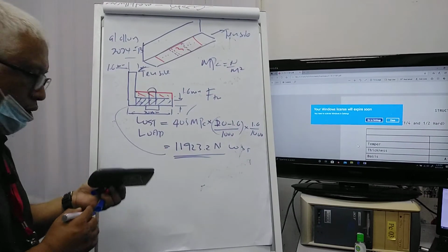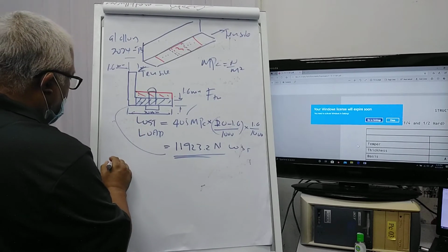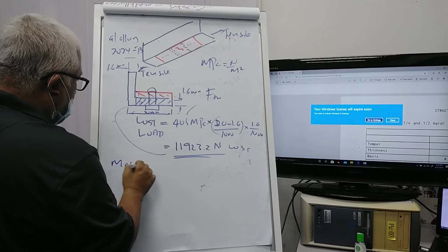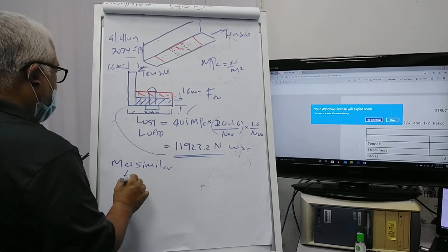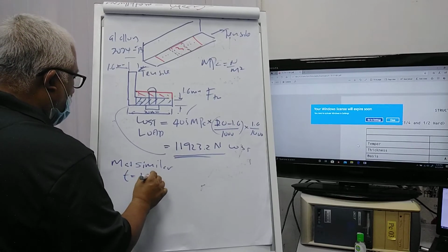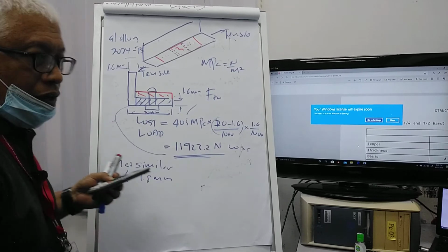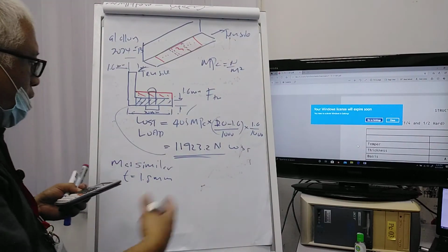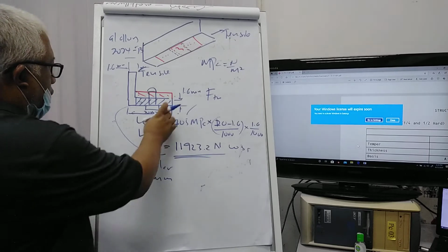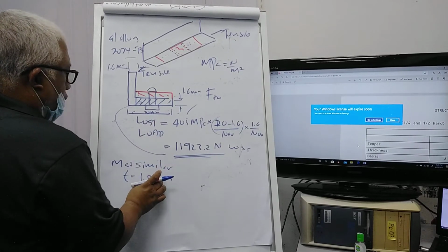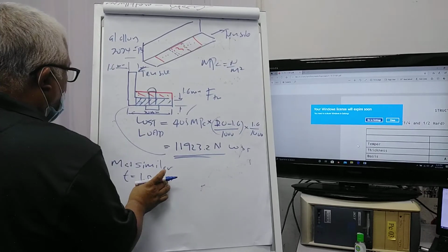So now our first attempt is a rule of thumb: material similar, thickness we use 1.8 mm as we have earlier followed the standard recommended practices, which is 1 gauge higher, but not necessarily this will solve the problem. We have to check first. So we have thickness 1.8.